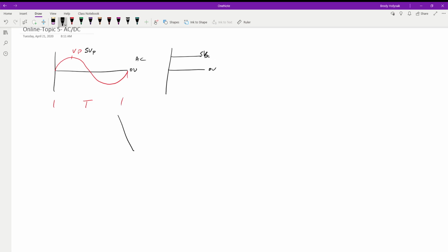If we take an AC signal and a DC signal and combine them together, we're still going to get our DC signal and our AC signal, and it's going to look just like this. But what we've done now is shifted where the center line sits. Before, this was sitting at 0 volts. Now, with the same values that we had before, our AC signal is centered and is now riding on a 5-volt signal.